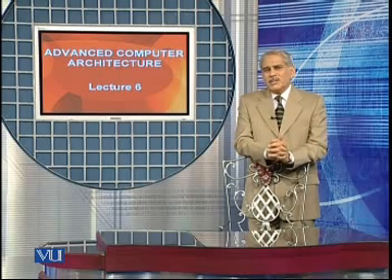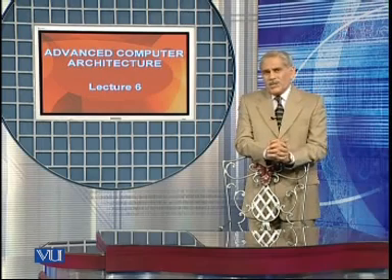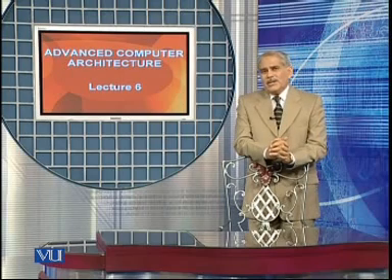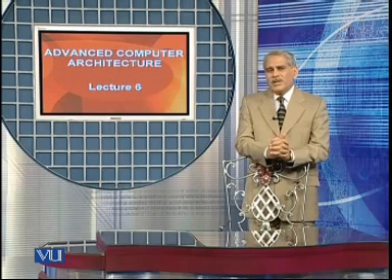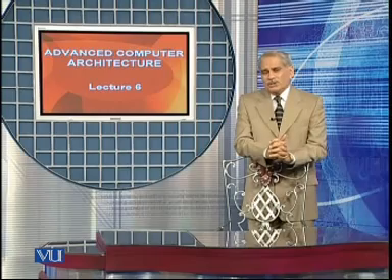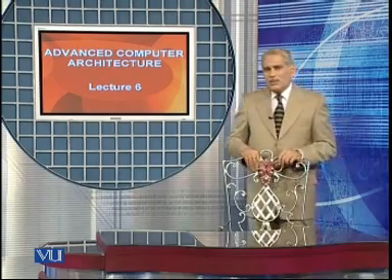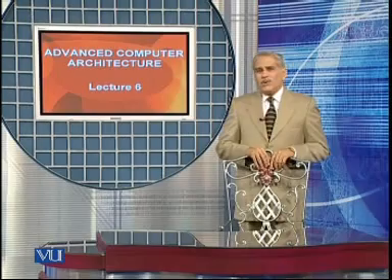The MIPS architecture is a 32-bit instruction word architecture, which supports 8-bit, 16-bit, and 32-bit operands. It has three distinct types of instructions which can be defined with the help of this type of instruction word. And these three distinct types are, first, the immediate or I-type instruction, where one of the operands is defined as an immediate operand.